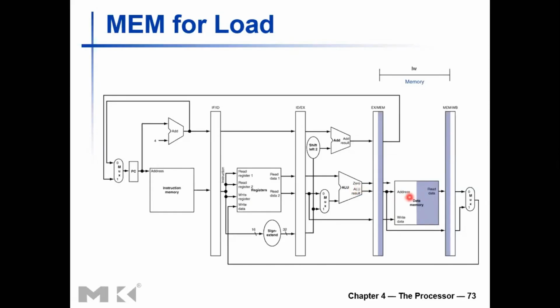So that instruction will not use the data memory in the mem access stage. It will just waste that time. But in the next clock cycle, you need to write that data into the register file. So that is why only in the case of a load or store instruction, this ALU result is a memory address and we use it to access the memory. In all other cases, the ALU result is a piece of data which might need to be written to the register file, right? Other than branch instructions, the ALU result needs to be written to the register file. That is why we forward that into the pipeline register.